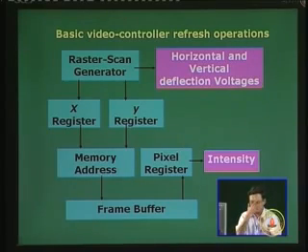So at that particular point, the deflection voltage of the horizontal and vertical deflection plates, or it could be the solenoid, the magnetic coil, which controls where the beam position currently is, is dictated by what memory you are accessing at the frame buffer. That is number one. And what should be the strength of the electron beam, whether it should be switched off, whether it should be switched on, the intensity of the beam.